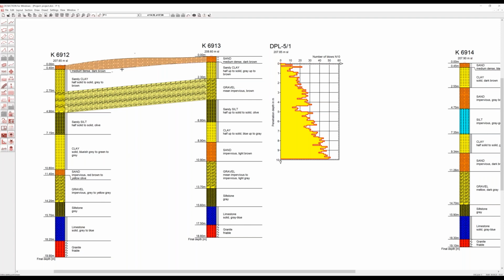And then the same again for the next layer. I can take these points here and fill this with clay. And this, as I told before, this may be arbitrary polygons. So here within this silt layer, there might be some lens.